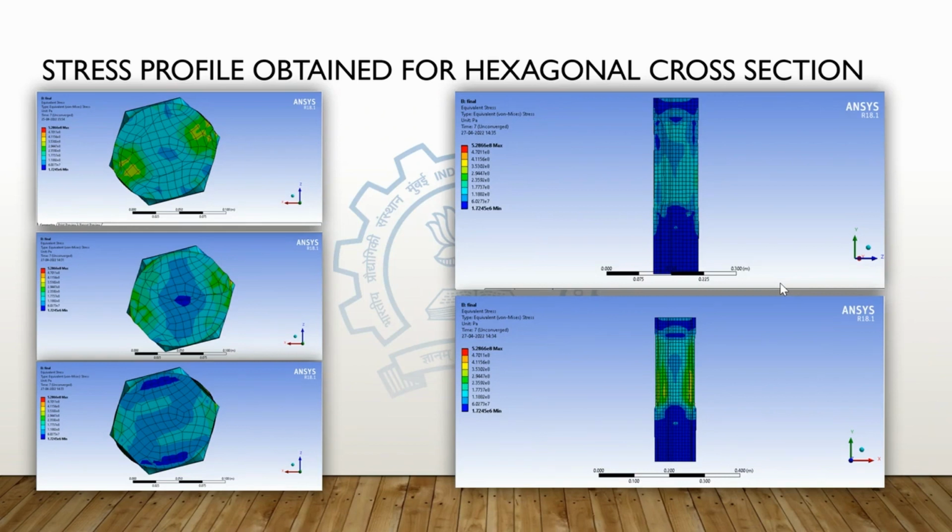Thank you, Adil. So, what we see here, as Arpit told, is that ANSYS converts a body into a mesh-like structure. We can see a net over the whole hexagonal workpiece. That is what mesh is. This is the mesh structure which ANSYS uses to solve the differential equations and apply the boundary conditions too. Now here we see various different cross sections, various axial cross sections and lateral cross sections also.